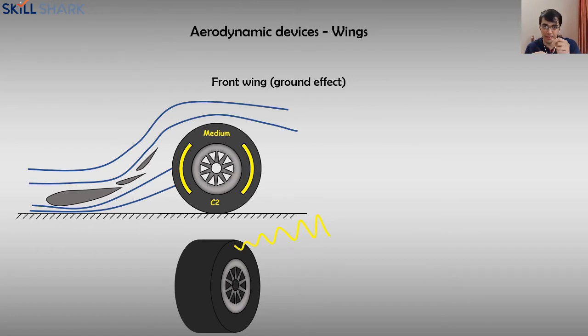You have that circular edge present, it's not sharp, but it is still an edge. Because of that, air tends to roll over the edges and create this sort of vortex. Vortices can be controlled, but turbulent air cannot. And vortices can tend to become turbulent air downstream of the flow. The issue with that is it can get in the way of other components that are behind in the car and cause a lot of drag. Also, sometimes if the vortices die out, it becomes stagnant air, which again causes high pressure, and it's an issue.